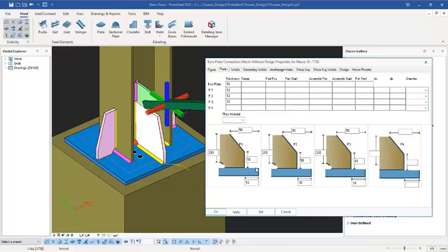Alright, so we have also the chamfer to be 50 by the height, and then by the length you have it to be 50. But for this one, because this stiffener is the one at the center or the width of the stanchion, so we always make that 100. Okay, just like this. If I click on apply now, you can see the changes right there successfully. Okay, so here the distance from the edge of the plate to the edge of the stiffener is 10 millimeters. Alright, so these are the necessary settings I did.